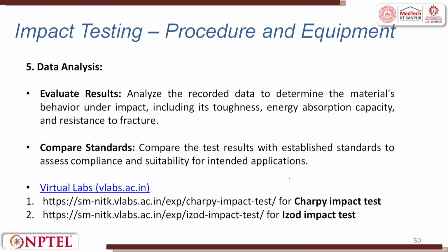Then we go for the data analysis, that is we evaluate the results, analyze the recorded data to determine the material's behavior under impact, including its toughness, energy absorption capacity and resistance to fracture. Then we compare the standards, that is we compare the test results with established standards to assess compliance and suitability for intended applications.